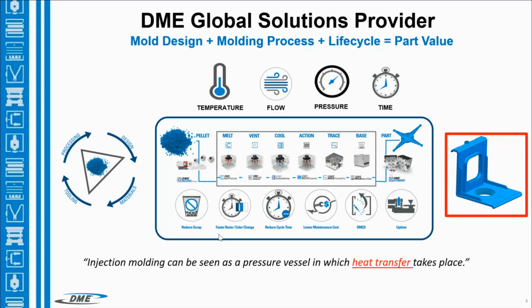And it really is based off of the 4 plastic variables that we all know in the industry: the plastic temperature, how we're going to flow that plastic into the mold, how we're going to pressurize it to get the right dimensions, the right cosmetics, and then the amount of time that it takes to cool that off and start the process again. And within DME, we bring a lot of different solutions to the table besides just a mold base or a mold component. And a lot of it is tailored around that melting, that flowing, that pressure and time.